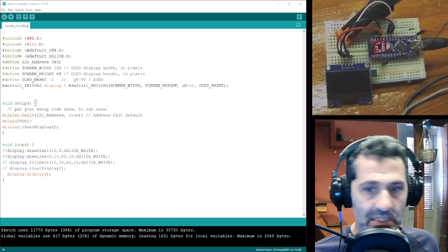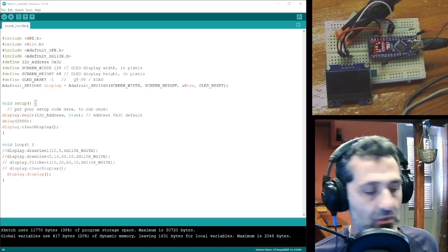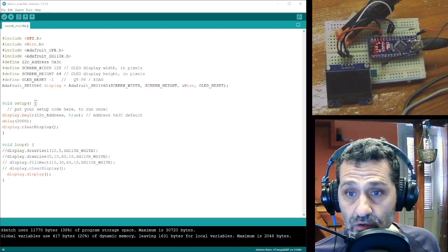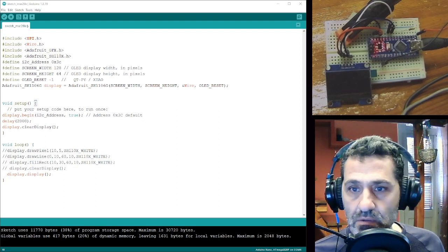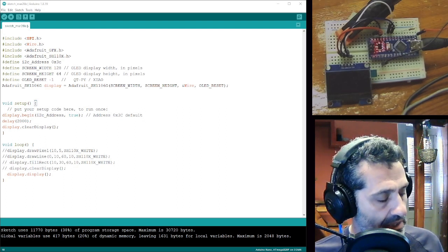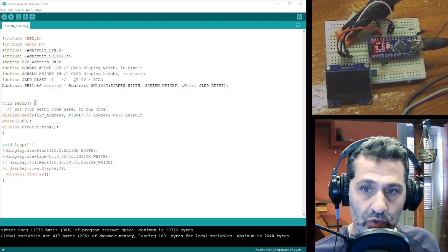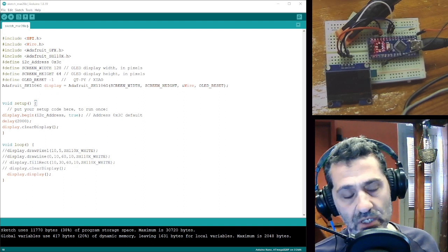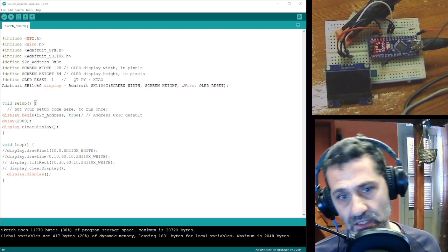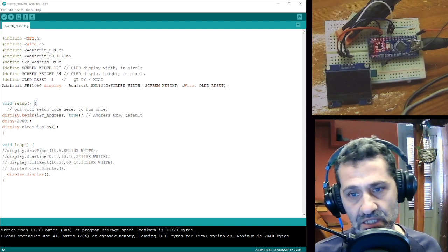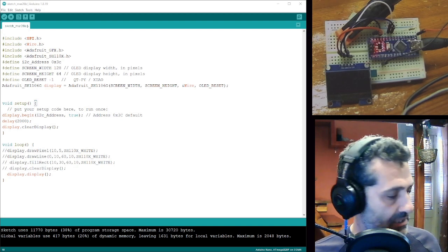Okay, the Arduino has some analog inputs, A0, A1, A2. I think from our setup here, A4 and A5 are already used for the OLED screen, so we have A0, A1, A2, but no big deal. We actually need up to 2 audio in signals. So let me show you what I have done here.